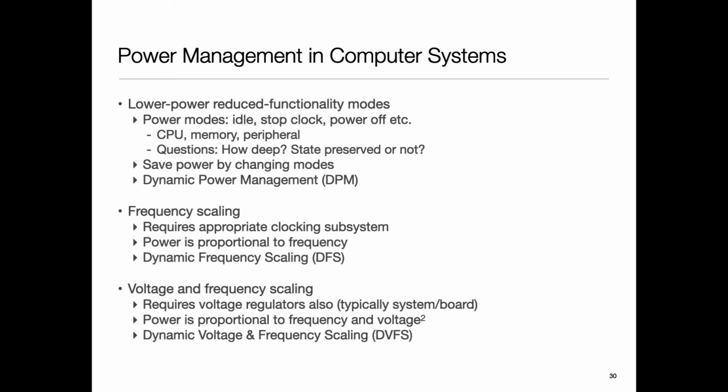You mentioned something called leakage power. The transistors in gates are made of diodes, and diodes, even when they're off, have some tiny amount of current which flows in the reverse direction. So there's always some current flowing. At a higher macro level, there are other examples of it. How many of you have heard the term vampire currents? Heard of it ever? No?